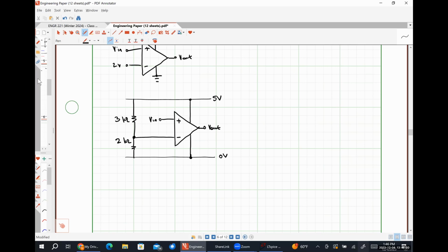That's going to put VX between this node and this node. It was originally between this node with terminal A and this node at the top left of the circuit, so it's still between those two nodes. So VX isn't really the voltage drop across the 10 ohm resistor, although it is the potential difference between these two points, between these two nodes. So it still needs to be between those two nodes if we were to do a source transformation.